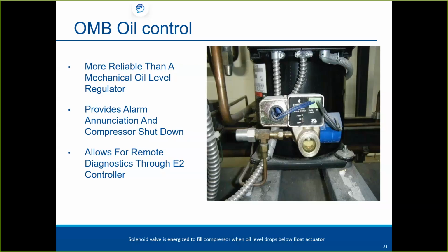The EEV will actually go back into an EEV controller. I didn't have that slide in there because I didn't want to get into too much. I was afraid to run over. But that will go back to a superheat controller, and it's based on pressure transducers and thermistors, okay? So the thermistor is similar to the bulb. Yes, it'll be clipped on there, very similar.